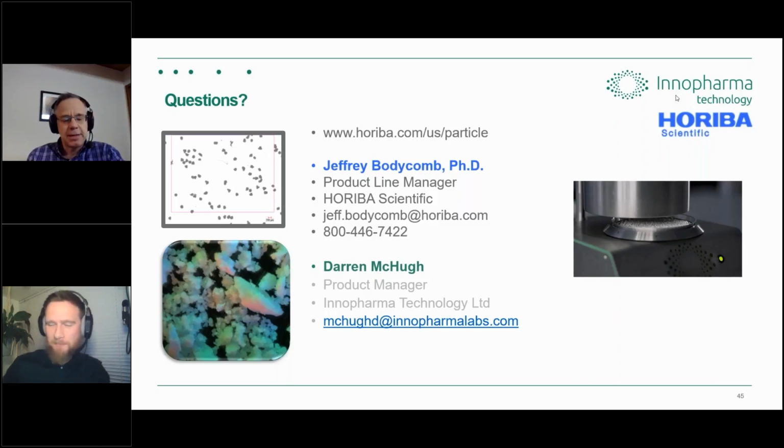particularly, is that if you have some very fine particles that came from dust in the air and don't belong in your sample, you can tell your image analysis system to just ignore everything under 2 microns. And it's fairly common to ignore stuff that's a single pixel size on your camera because that suppresses camera noise anyway. So you can help yourself a little bit with setting rules for what you accept as a relevant particle. Now, of course, if you set that rule, that means that if any 2 micron particles work their way into your sample, you'll never see them.